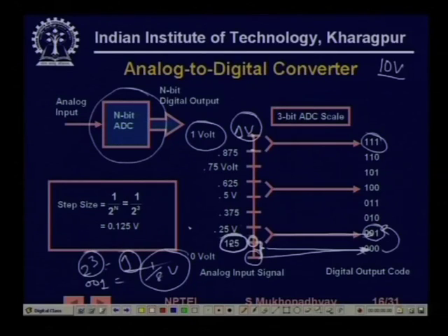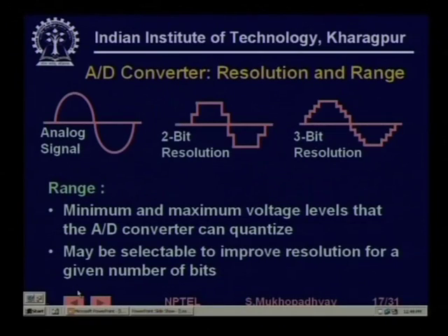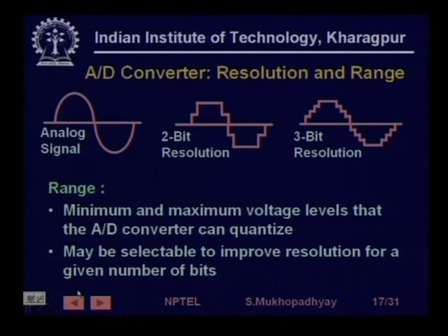Let us talk about unipolar signals, not negative. So, suppose 0 to 1, if you have a signal, then always you will get the value 0, the variation will not be caught at all. On the other hand, if you had amplified this 1 volt to 10 volts and then taken care of this amplification factor in your software, then this 1 volt signal variation would have been captured up to 3 bit resolution.